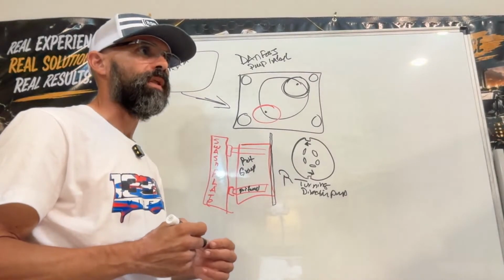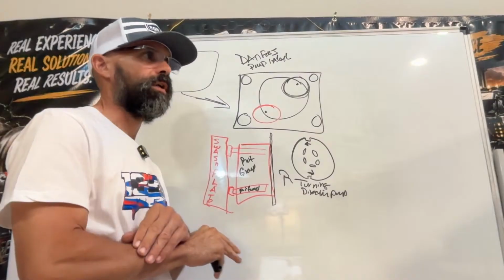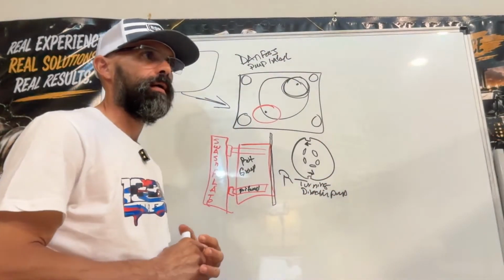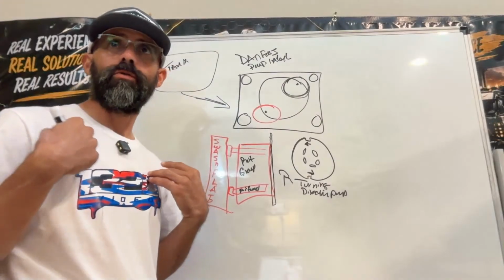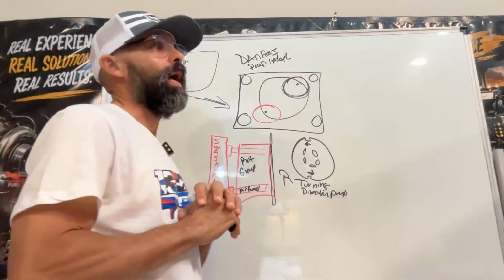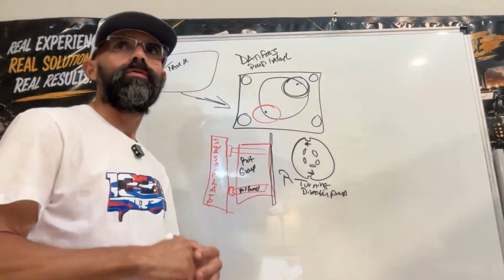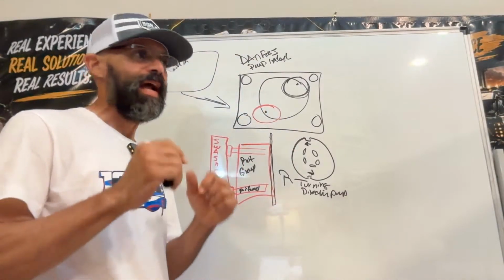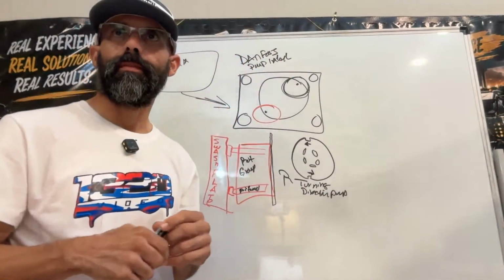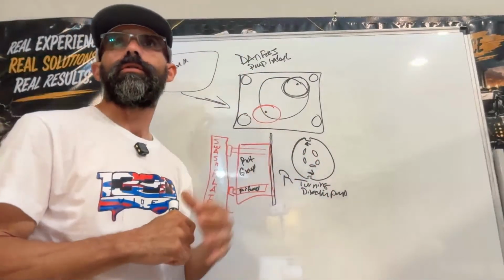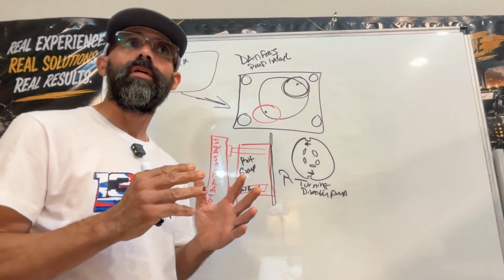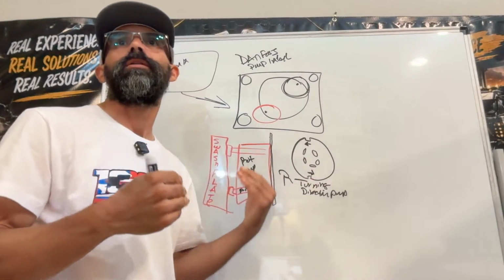So just clean surface, clean table, disassemble everything. And what I do before I disassemble a pump, I clean the outside housing completely. I cap off everything. If I disconnect the lines from the pump, I cap off the ports. That way, when I wash it, I don't introduce any foreign material or contamination into the pump.